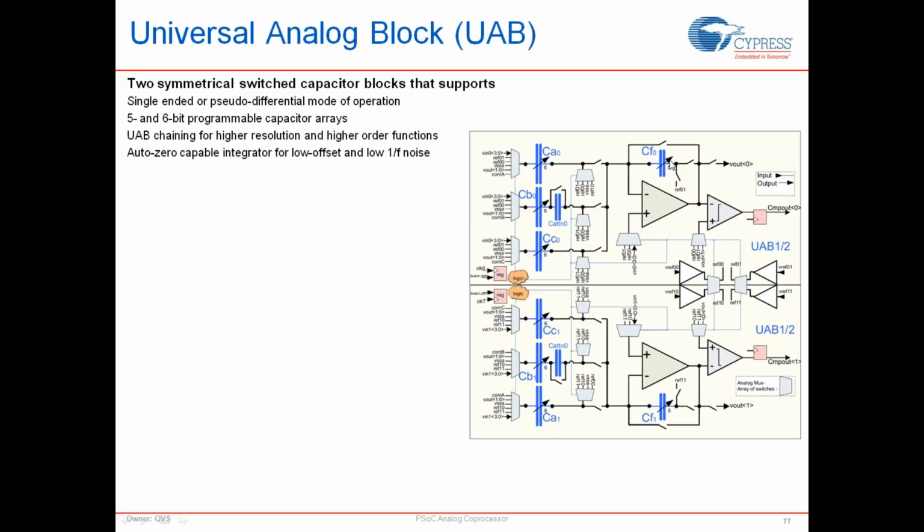You could also have multiple input channels, or I would call it multiple input capacitors. And each of those capacitors could themselves be depositing charges in the same phases or alternating phases. Depending on how they are phased, you're either adding or subtracting those signals themselves. So now you could have two signals coming into the CA and CB capacitors, which are switching in complementary phases, effectively having a difference of the two signals. If you're on the same phases, you're implementing a summer.